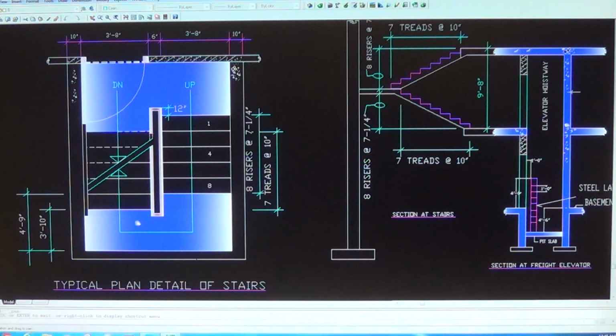And the landing right here, this is the landing. The landing, when you turn the stairs, when you turn to other direction, this landing here should be extended. It's supposed to be right here. It should always be extended up to 1 tread, the size of the tread. Do not start the riser from here, right here, in line with the other riser.